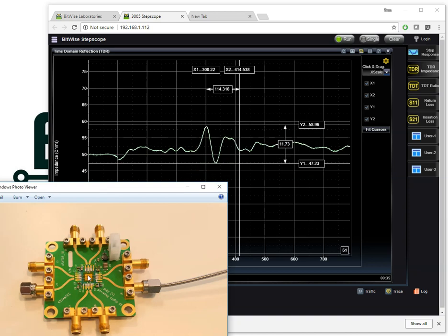exposed wire that is pressing here, the first one is this inductive spike. This capacitive spike would be right here, while the wire runs right over a ground plane and is only separated by a thin piece of tape. And then as I continue on the other side of the device, I can see other impedance loss on the output trace down here, to the point where I finally get to the output signal.